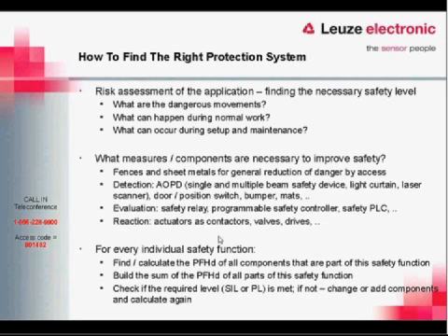As we said before, when you do a risk assessment, you need to have everybody involved with that machine there. You need to be able to talk to the maintenance people. You need to be able to talk to the operators, because everybody does something different with the machine. So you need to find out what tasks are involved that they do on a normal basis that could get them injured. Then we can start looking at, well, what measures can we do to negate these risks?